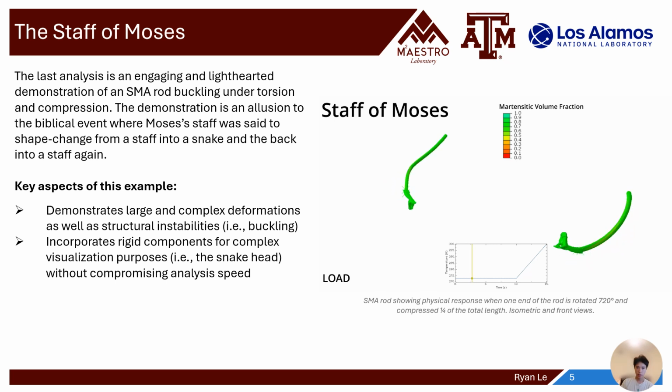So we can see that we're loading it and it's causing quite large deformations, but when we heat it, it recovers completely with no irrecoverable strain.